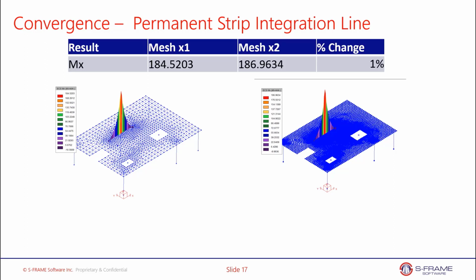The strip integration lines are also useful for calculating the steel areas by creating a section of grids of strip integration lines. This is similar to how the codes work by defining regular grids. Now, contouring and strip results are all dependent on mesh densities, the model sophistication, and the methods used to calculate or average out the analytical peaks.